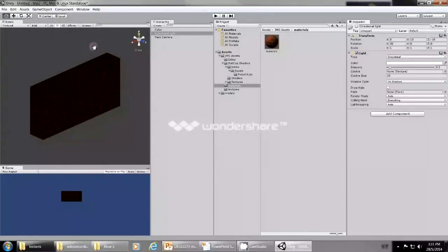The ambient lighting was turned off because I introduced a directional light into the scene. So automatically Unity turns off the ambient lighting to be able to show you the effects of the directional light. If I turn off the directional light, everything goes into darkness. I turn it on by clicking on the checkbox for the directional light in the inspector view. It comes on again, so you can see that the wall is lit according to where the directional light is located.